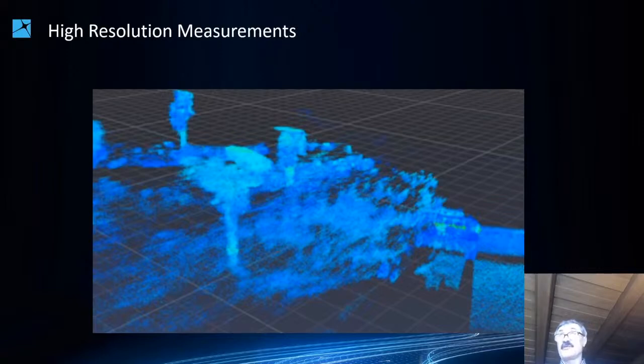So this needs to be improved further. But in case we have such a capability just to accept all the data which the LiDAR delivers, then we will see something like this. This is a 3D high definition image collected by the sensor, where the number of channels, acquiring channels, was emulated by the moving of the LiDAR in the vertical plane with an additional scanner.